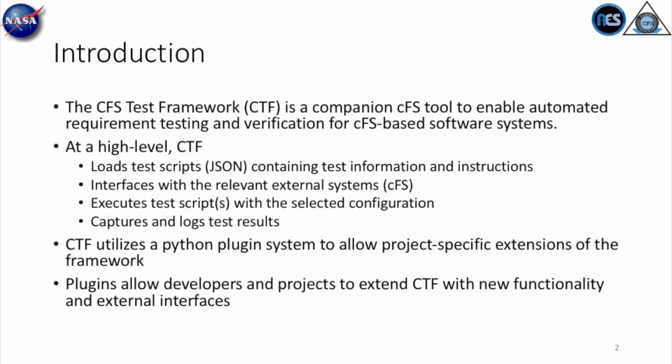At a high level, the CFS test framework, commonly referred to as CTF, loads the test scripts, which are written in JSON and contain the test metadata and instruction. CTF then interfaces with the relevant external systems, such as one or more CFS cores. CTF will then execute the test scripts against the selected test configuration, capturing and logging the test results in the process. CTF is written in Python and utilizes a Python-based plugin system to allow developers and custom projects to extend the functionality of CTF as needed.